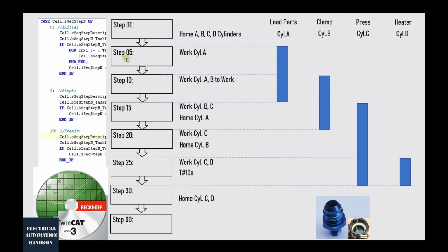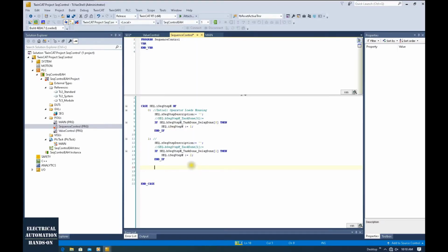I will use a step of 5: 5, 10, 15, 20, 25, 30. As we know, scope creep happens in every project. So using this step of 5, between the current step and the next step we have 4 spare steps. If the customer asks for additional tasks between the steps, we can use those 4 spare steps to program the others.